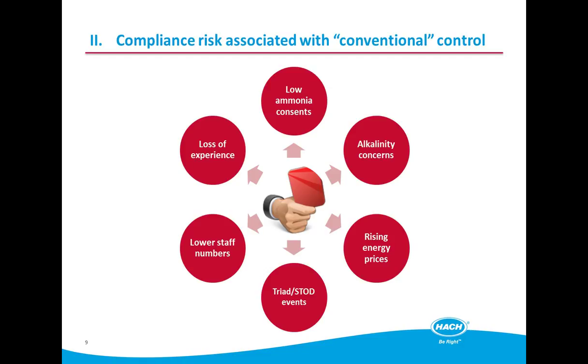Energy prices are likely to remain changeable in the future and probably more extreme. Stud or triad periods are big opportunities to avoid elevated charges, but care needs to be taken when reducing energy consumption through these periods. Simply turning off aeration or reducing aeration without consideration is again a very risky strategy.